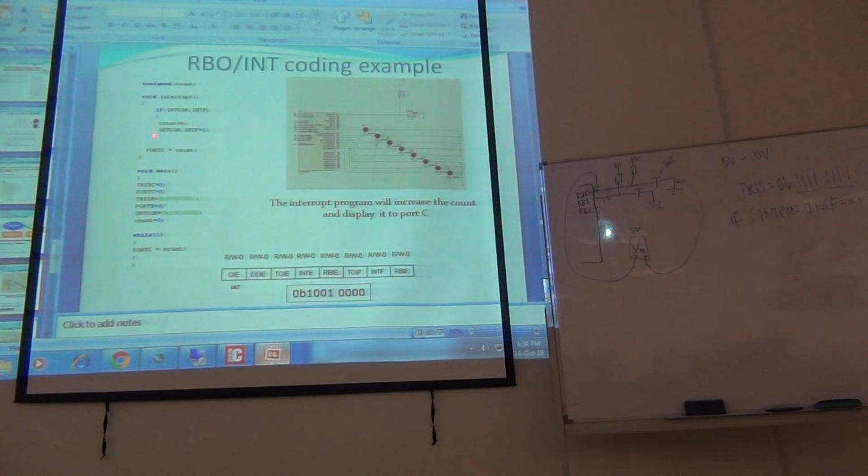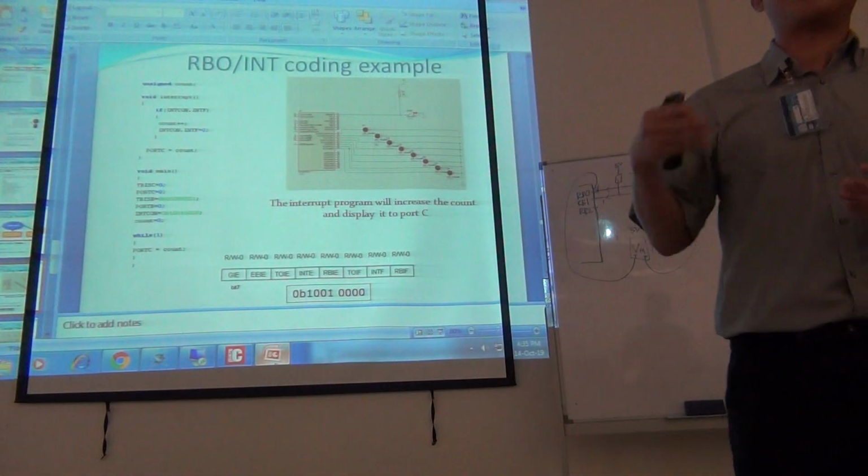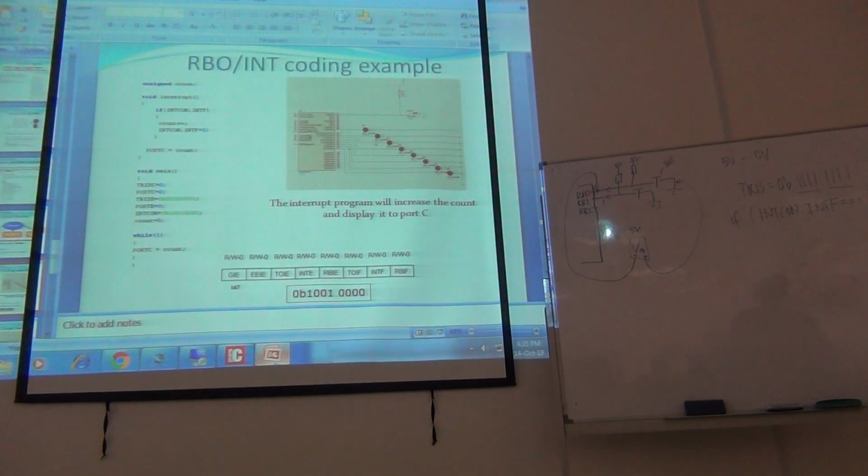Just now you input this one, right? You change it to delay underscore s. You can see the result is still actually delayed interrupt. Because you do not have this command, the system thinks that the flag is always 1. It's saying that it always has an interrupt, so it has to go to the interrupt function to execute. So this command is very important. This command is to clear back the flag bit of the interrupt for RB0. Can you see it or not?